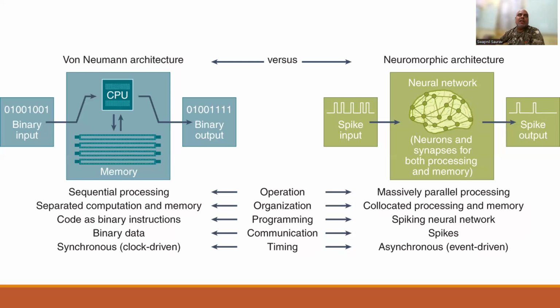Inherently scalable. Neuromorphic computers do not have traditional roadblocks to scalability. To learn larger networks, users add more neuromorphic chips, which increases the number of active neurons. Event-driven computation. Individual neurons and synapses compute in response to spikes from other neurons. This means only the small portion of neurons actually processing spikes are using energy.